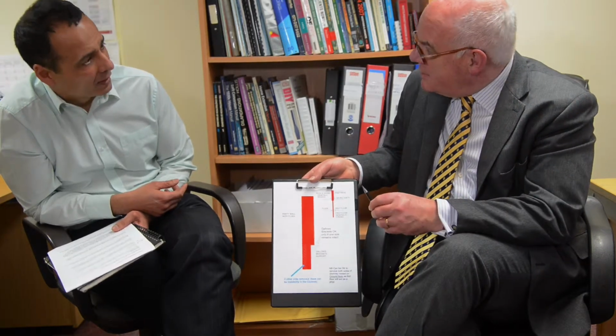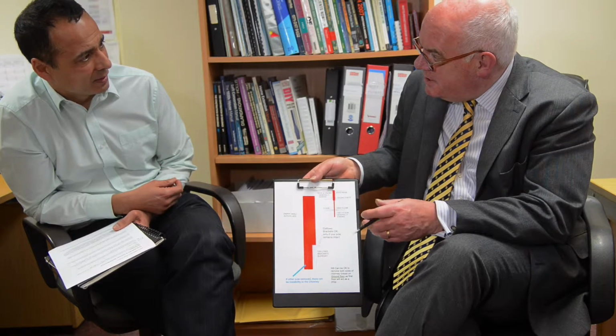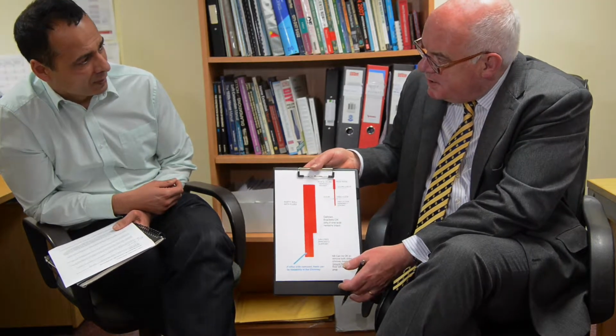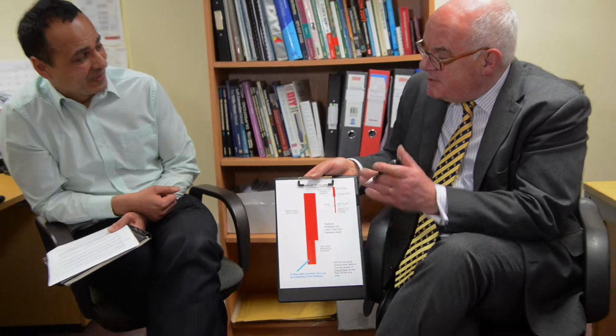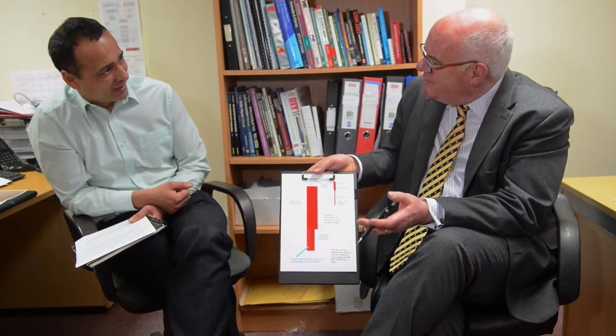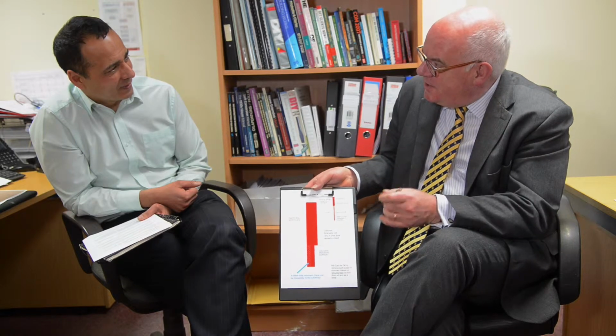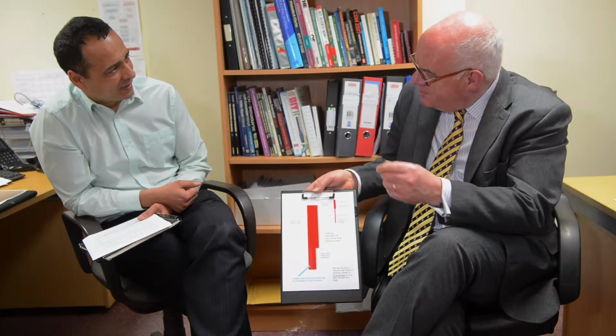You've probably seen it in the news. Absolutely, after serious gales. So this is something that needs to be taken quite seriously, particularly if the chimney stack hasn't been properly maintained, so even higher risk. Yes, because right at the top of the building, they've been burning quite sulphurous coals over the years. You get sulphate attack on the mortar. The sulphur in the coal condenses or deposits on the inside of the chimney stack. A bit of rain, a bit of moisture, and you're getting sulphuric acid eating away at your mortar. So these chimney breasts can actually be in quite poor condition.